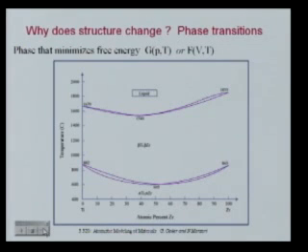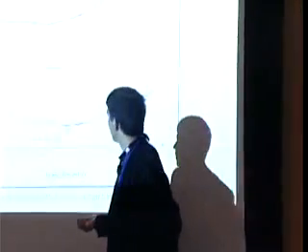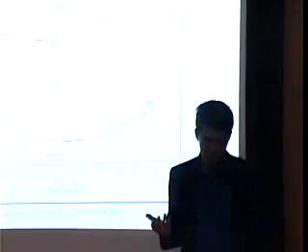Okay. So that was the example of thermal expansion. So there you had to worry about phonons, maybe electrons. Here's another example where you would absolutely need a temperature-dependent study. Here's the phase diagram of titanium and zirconium. Titanium and zirconium are both hexagonal close-packed, HCP, at low temperature. At high temperature, they're actually both BCC. And so this is the transition temperature on the titanium side. This is the transition temperature on the zirconium side.